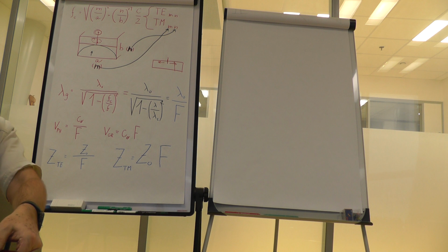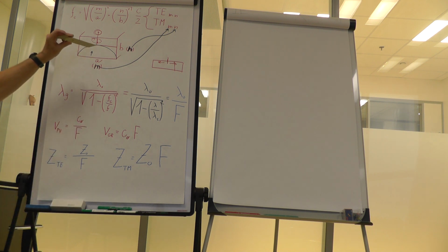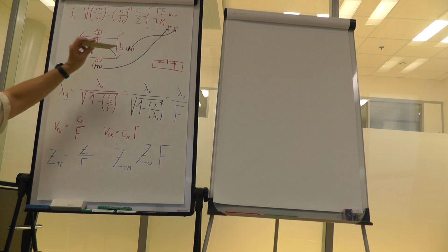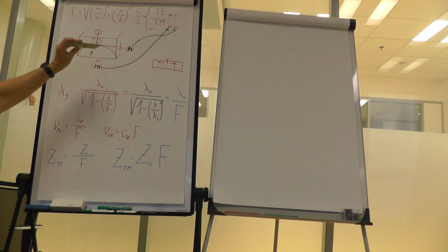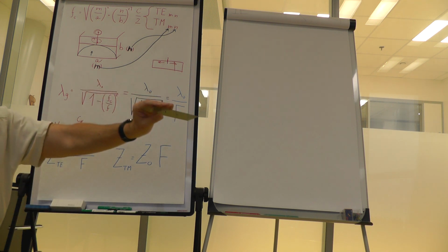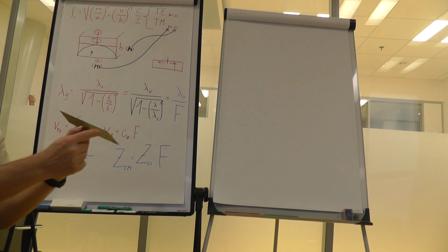Now if we move that into the middle of the waveguide, then the situation is completely different. We have moved a lossy material to the maximum electric field, and therefore there are maximum currents induced by that field in it, and that causes losses. So we have a variable attenuator just by moving this piece of material from the wall to the middle of the waveguide and back.